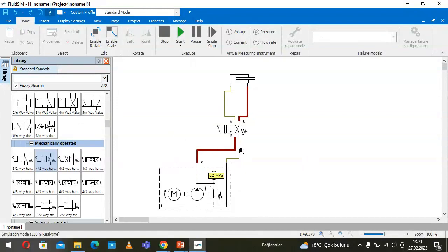So then we said this is a two-way valve used mainly in hydraulics, and we learned also that we don't use this valve in pneumatics. Instead of that, we use a 5/2-way valve in pneumatics because of the speed of pneumatics.